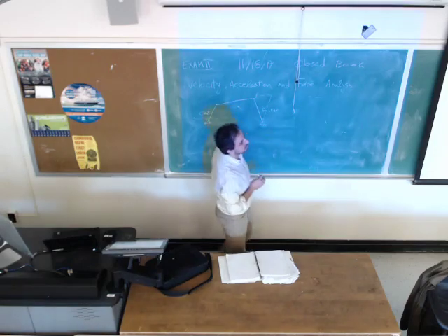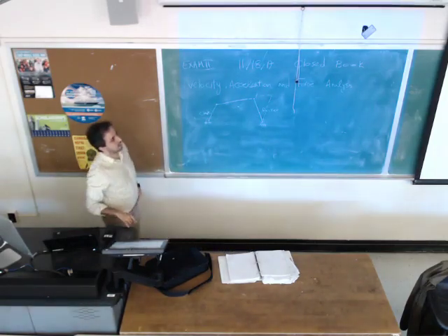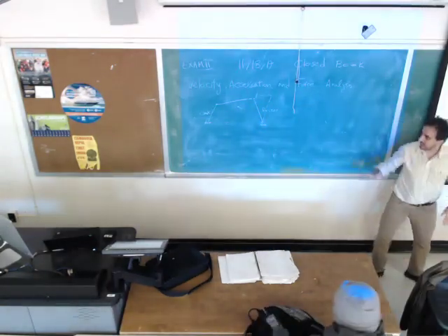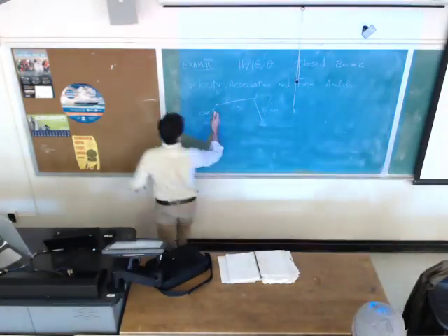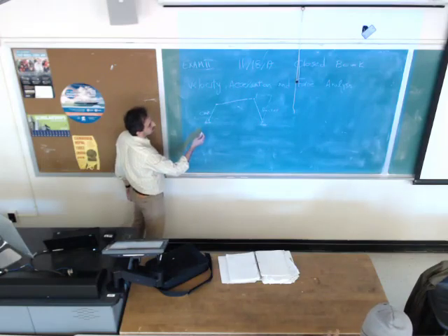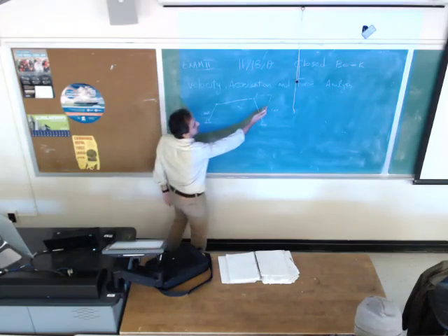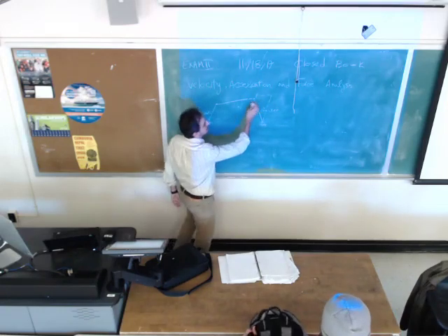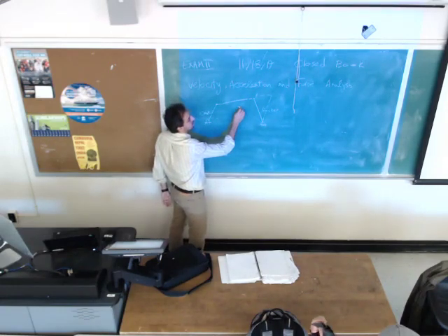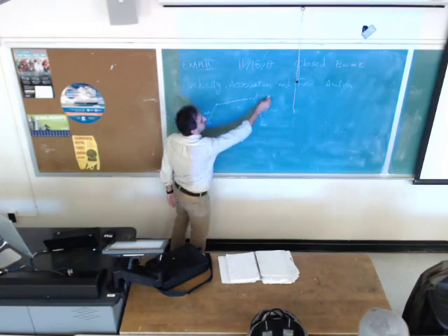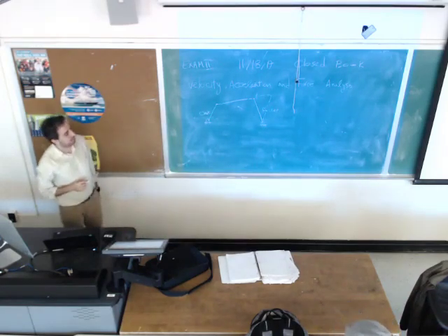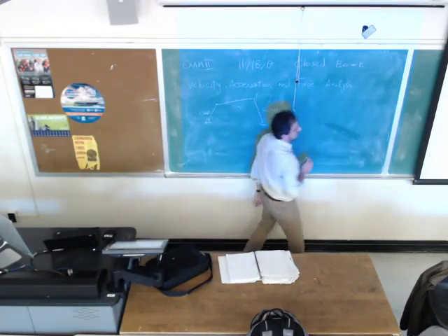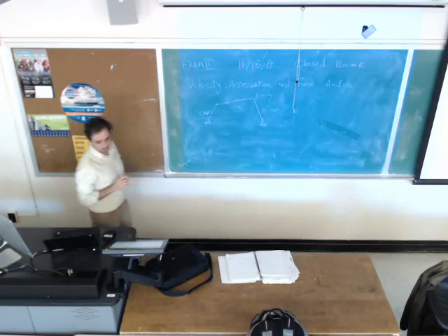And it's a mechanism with the timing ratio equal to 1, meaning that the time it takes going from this point to the other extreme point is going to be the same as the time going back from this extreme point to the starting point. So this is what I mean by timing ratio equals 1.